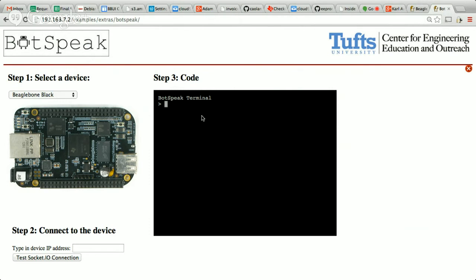Okay. So we get tokenized on the ARM, but then all the actual commands would get sent down to the PRU for execution. And the huge advantage is that instead of taking up ARM cycles and having unpredictable timings, they would all have extremely reliable timings because they would be running on a dedicated processor and not chewing up the ARM CPU cycles.